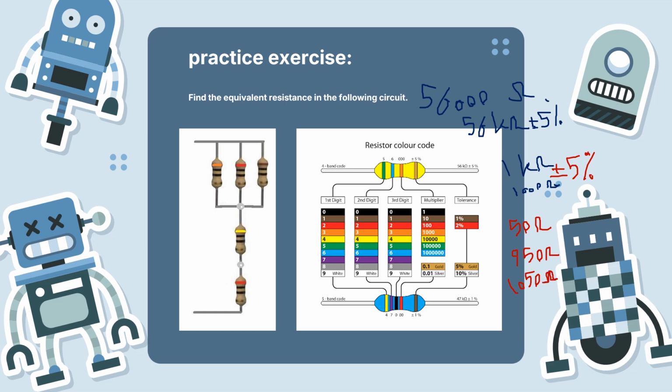So if we read the resistor with a multimeter, we can see, for example, 1020, and in another one we can see 970. Because of the tolerance, it's not an exact and accurate resistor. But if the tolerance is 1%, then again, for the 1 kilo ohm one, we can see 1000 ohm plus minus 1%.